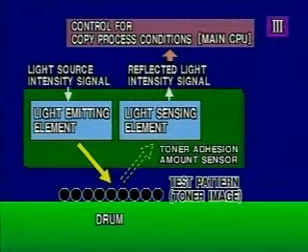A 14 by 50 mm half-tone pattern is developed on the drum when a pre-run is completed, or when 2,000 copies are made, and then its density is detected by the toner adhesion amount sensor. Thus, by reflecting the result of the density detection throughout the process controls performed by the counters and thermistor, the image can be better maintained.